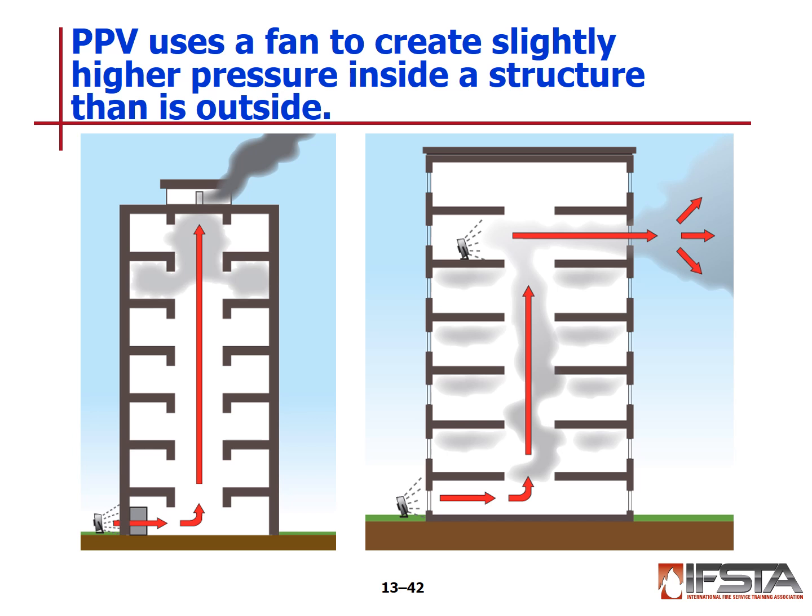So in the first instance, the fire's up there in the top 2 floors. We've opened up a doorway up top to give it an exit point. We set up our fan, and because of the travel path, it pressurizes and pushes it all out the top.